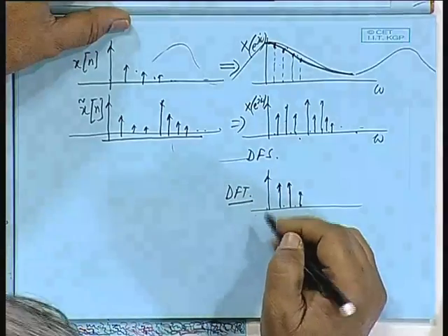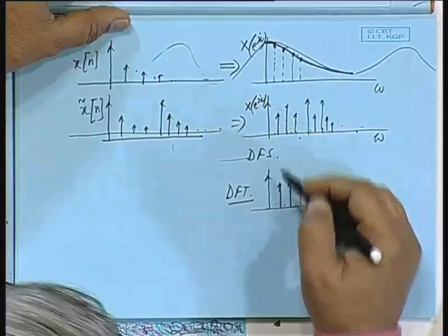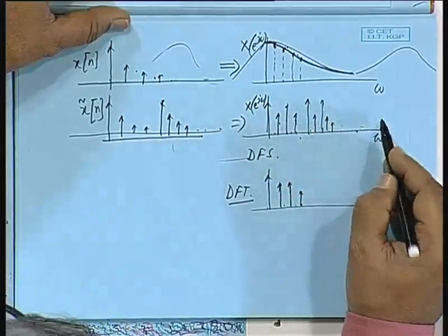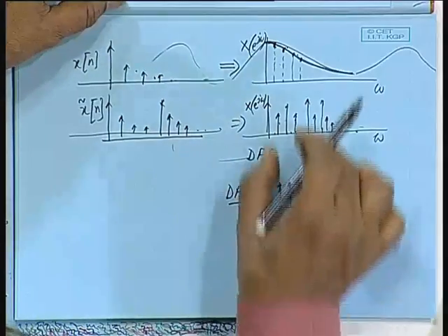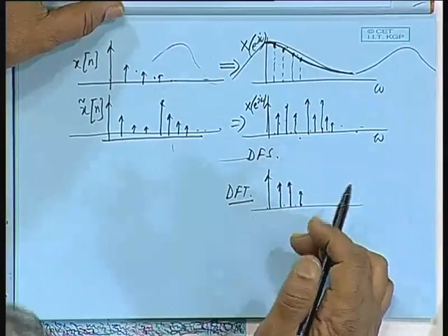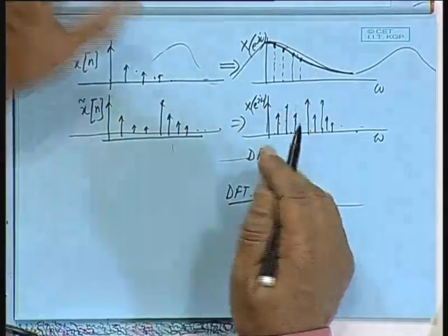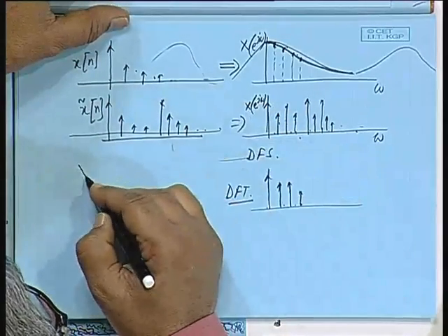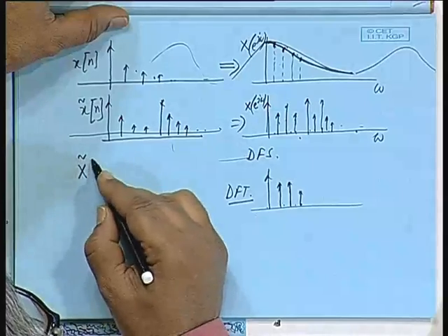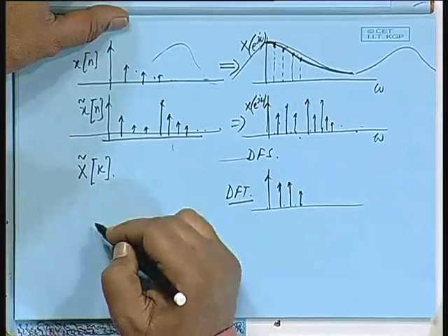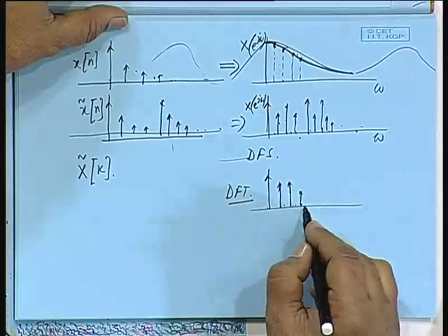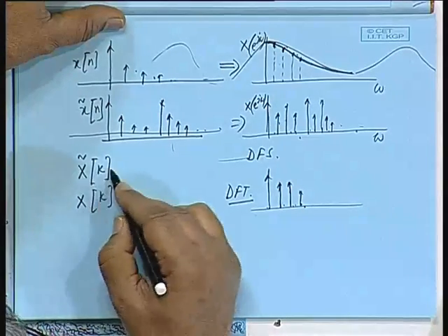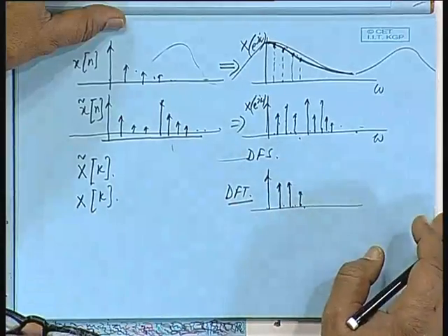All right. So, for discrete Fourier series and discrete Fourier transform, these magnitudes are identical, the only thing is that here it is periodic, while here it is just one set, one of the periods we are taking. So, so far as the mathematical relationship is concerned, they are identical. For discrete Fourier transform, we just put k equal to 0, 1, 2, 3 if it is a 4-point sequence, and for DFTs we write X k, but the expressions are identical. Okay.